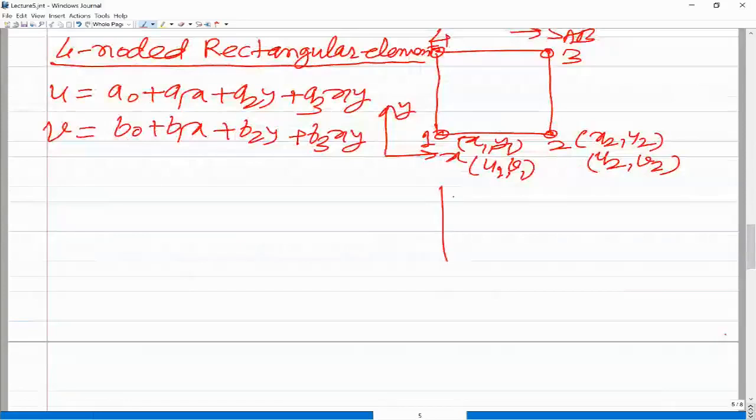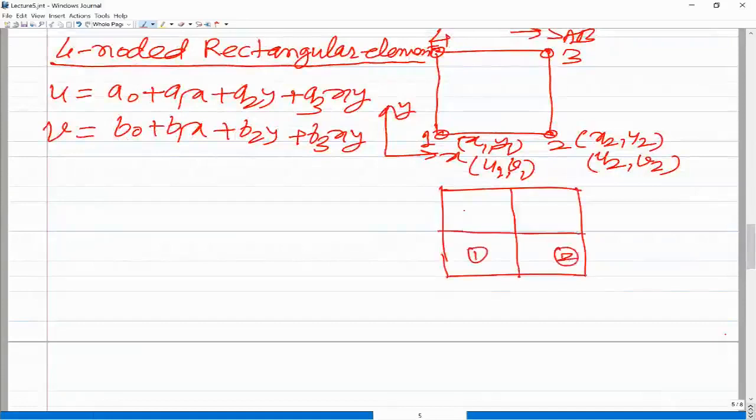So now let us say we have a domain. I may discretize this into, let us say, four elements. So this is element 1, this is element 2, and let us say this is 3 and this is 4. And now if you see again, when we talk of common boundaries, you can take any common boundary. Let me take this AB. So along AB, and let us say here this is x and this is y coordinate, along AB your y coordinate is constant.